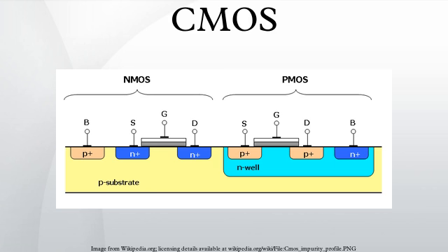A special type of the CMOS transistor with near zero threshold voltage is the native transistor. Tunneling current through gate oxide: SiO2 is a very good insulator, but at very small thickness levels electrons can tunnel across the very thin insulation. The probability drops off exponentially with oxide thickness.